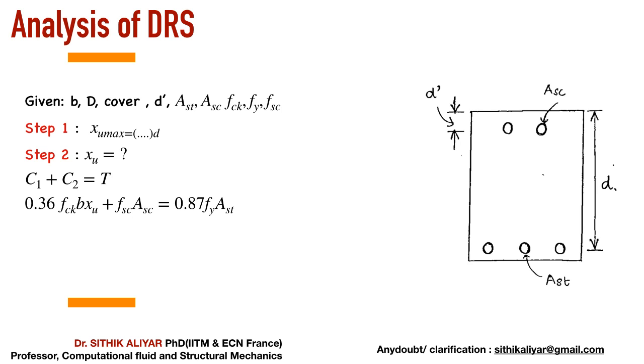Analysis. I hope I already told you, somebody is going to give you a beam. They are going to show you some beam, and they can ask you a question like: how much moment can the beam take? Visually you can see the width, depth, and cover they have provided, and the number of reinforcements. So they will ask you a single question: how much moment can the beam take? Obviously, if it is a 300 beam with 3 bars of 20 mm and 3 bars of 16 mm, the moment will be approximately in the 150 to 200 range. Answers will be in that range.